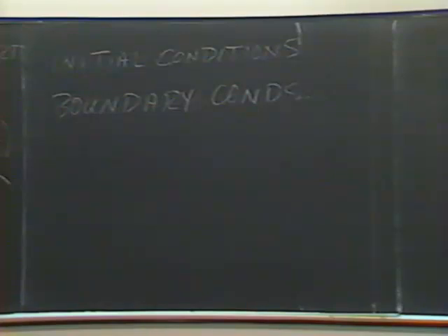D, the dispersion coefficient, I might say before we get into it, this term is hypothesized. It's not really a description of the physical processes. If we could describe points close enough together, if we could describe them a few centimeters apart throughout the system, we could probably eliminate these terms. These terms assume that the mixing processes can be described like those of molecular diffusion. That is, that they're completely random processes, and that the transport is due to the rate of change in concentration, or the gradient of concentration, that it's proportional to that gradient in concentration.